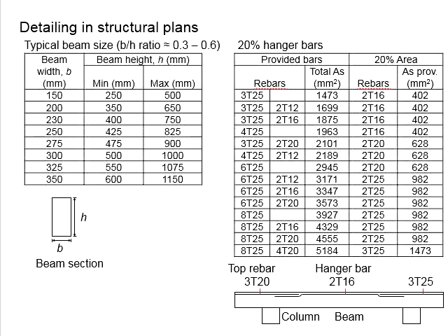So you only require the minimum reinforcement bar as a compression bar, which based on industrial practice, the smallest size that you are going to use is T12, and you require a minimum of 2 units, one at each corner of the beam. Ultimately, you will have this hanger bar as 2 T12.